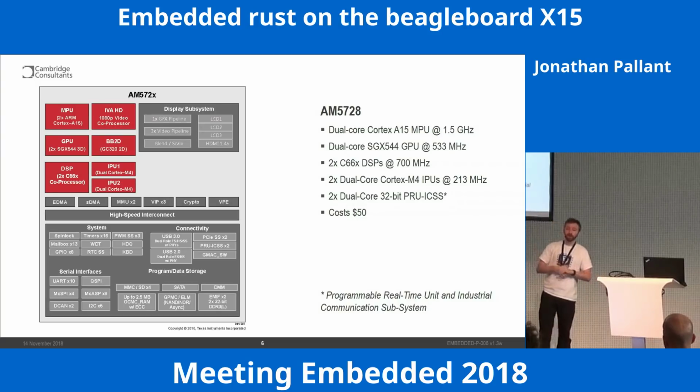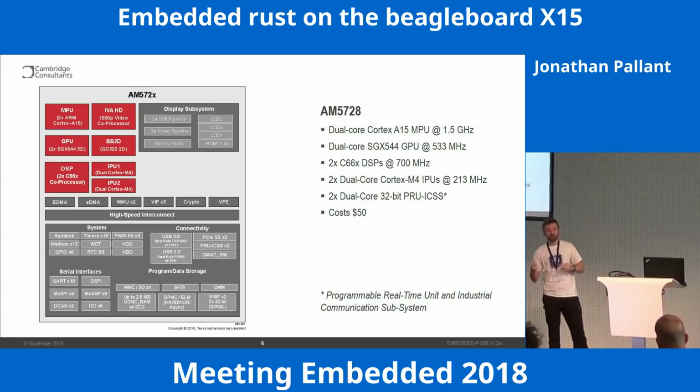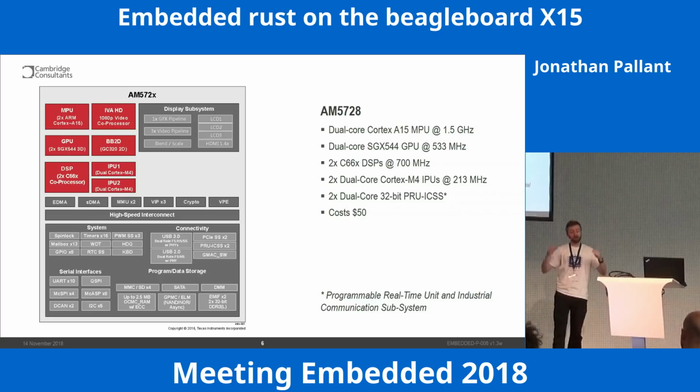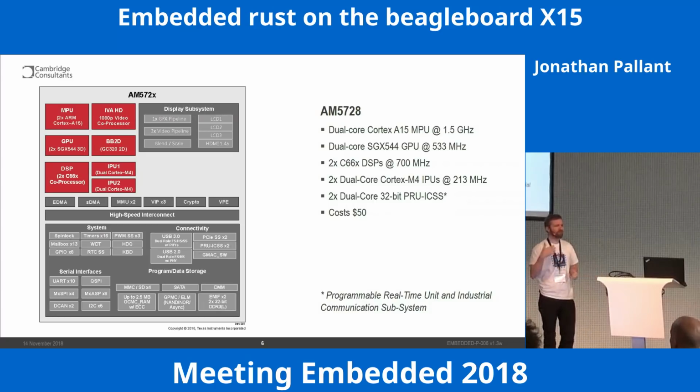We've got two Texas Instruments C66 DSPs. These are excellent at mathematical computation. They're not so great at branching. But if there are mathematical routines you need to run, video compression, filtering and analysis of sampled RF, you could run that on the DSPs.